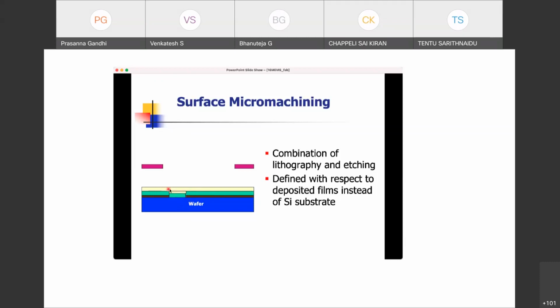Then this yellow color is a photoresist that is spun on the surface to create the dimensions of your cantilever, and you expose that. Then you develop the photoresist and etch away the remaining part of the deposited material. Then you remove it, or ash. The asher is a process where you burn out this polymer, and what remains on the surface is your standing cantilever.